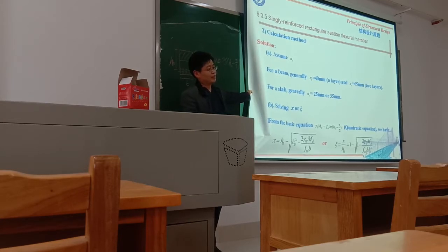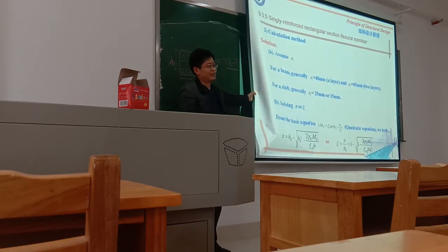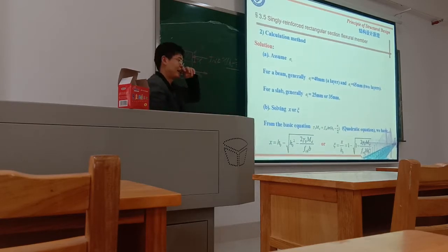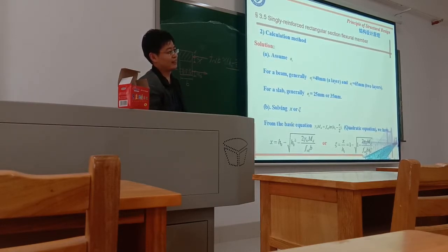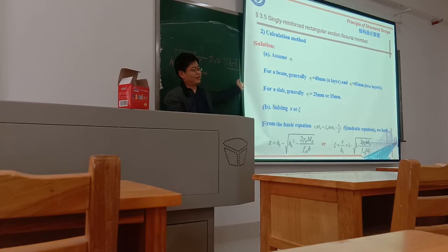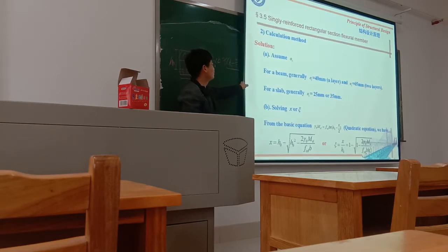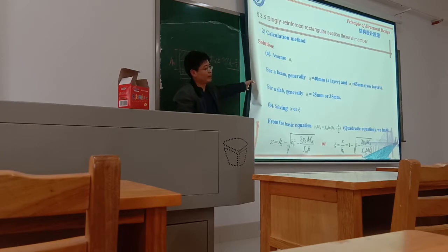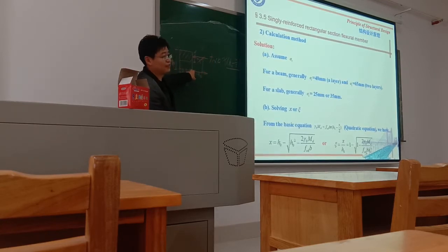It is the distance, the reinforced distance minus half of the concrete compression distance. So this part, FCD times B times X, is the compression force, and H0 minus half x is the arm of the compressive force to the tensile reinforcement.